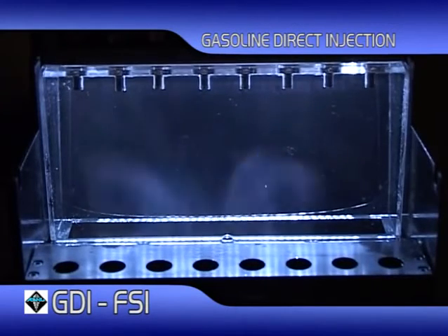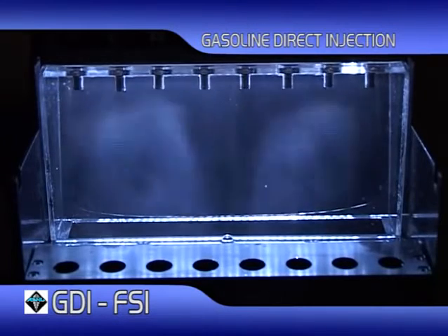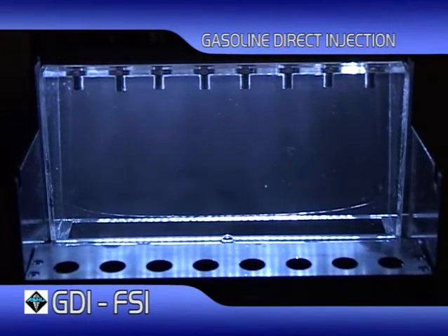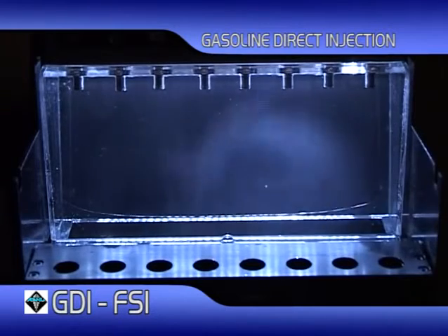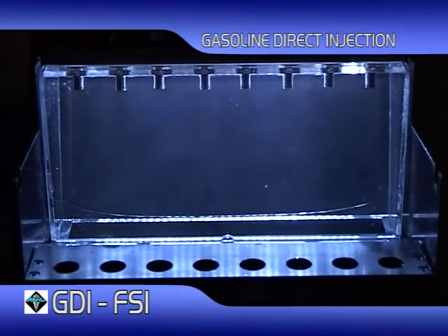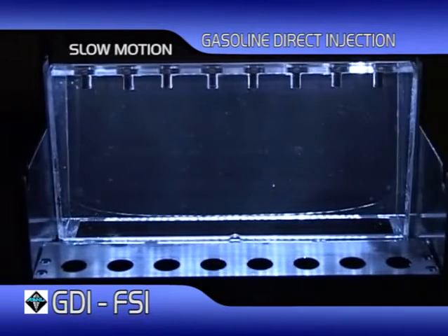The location of the injector, in conjunction with the shape of the piston, will determine the required shape of the spray pattern. With the wrong spray angle, the fuel will not mix with the incoming air, the process of correct combustion will fail, and the lambda control will take action to correct the problem, taking drastic action to protect the system if required. To help show this better, we have slowed down the clip of these injectors spraying.